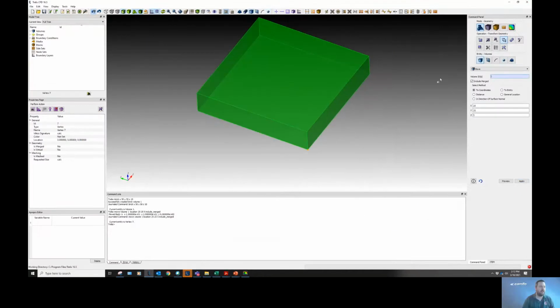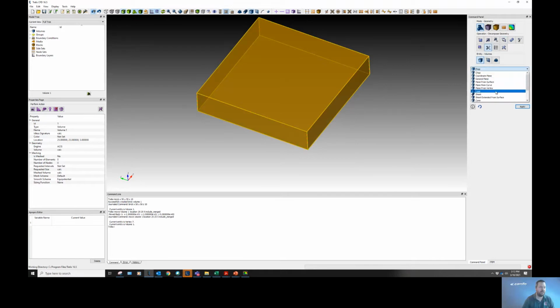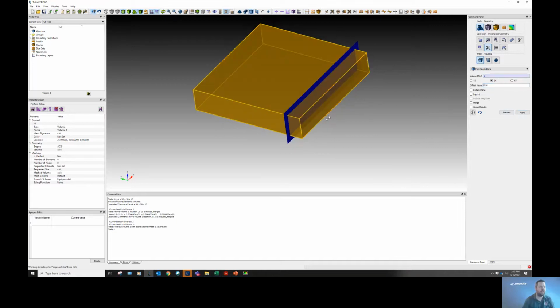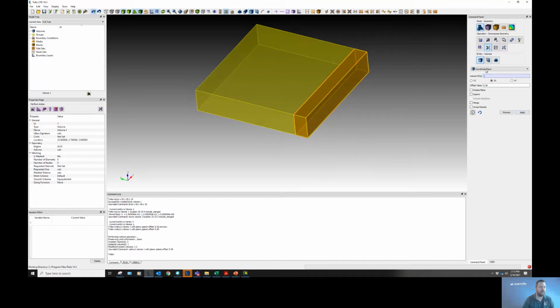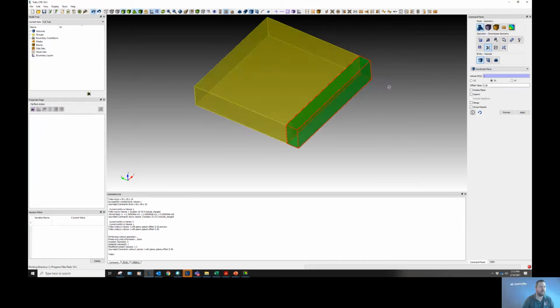So if our passes are 5.56 feet, there's a couple different ways to cut this out to define the walls. We can cut the tank assuming a 2D wall, and the XZ plane. And so if we pick 5.6, it would cut the model here. That would be one way to do it. If we wanted to make a wall with a thickness, we could create a wall and subtract it from the domain. There's a couple ways to do it.